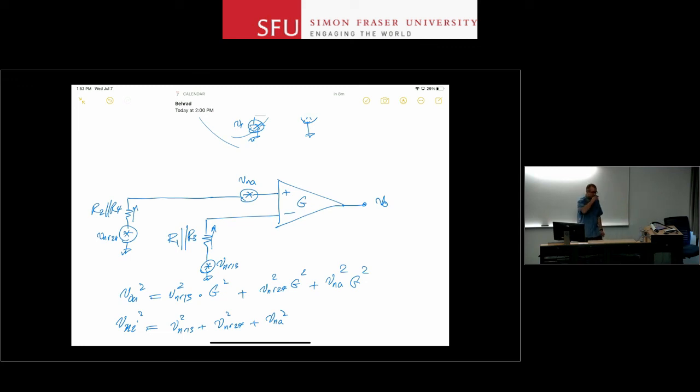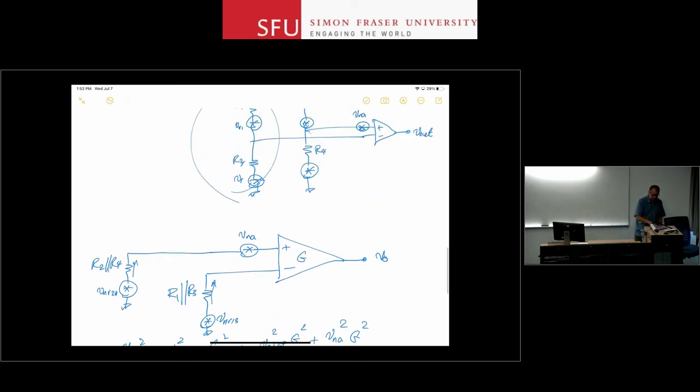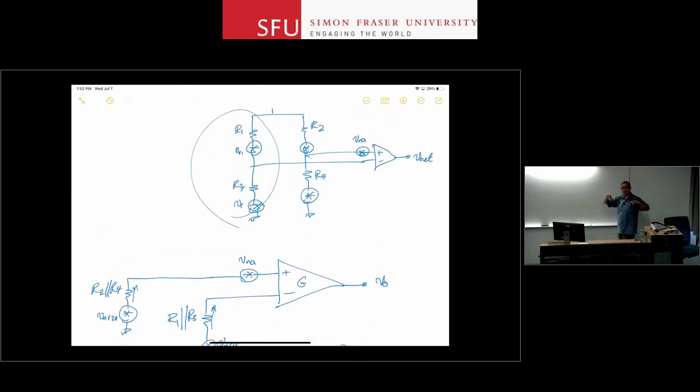You can calculate the mechanical noise right here. You have the sensitivity of the system. So what you can do is say this much equivalent acceleration produces this much noise at the output. You can bring it back to the input of the amplifier, or you can keep everything at the output and compare and see how much the total noise of your system is. And that's the noise calculation, right?